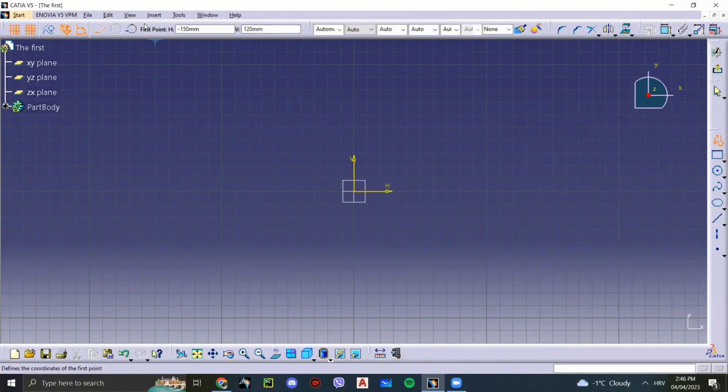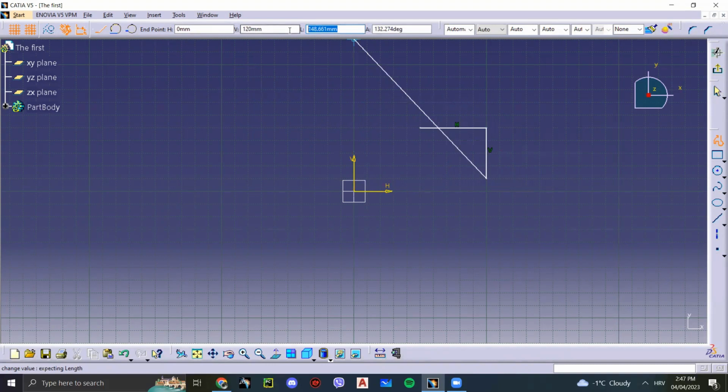Right up here, you can see this little table. It's gonna be showing some basic information. So we need our first point. We can choose it to be whatever we want. This is the 0 point, and let's choose the 50th point. And now we can choose in which direction we want to go. Let's go here. Here, we can also choose the length. Let's make it 20. Now it's 20. We can choose the angle. Let's make it be 0 degrees. And we gotta watch out. If we move our mouse while doing this, it's gonna change our value. So keep it here. There we go.